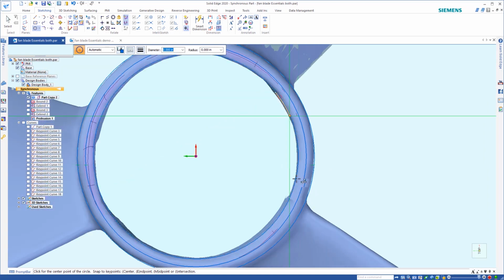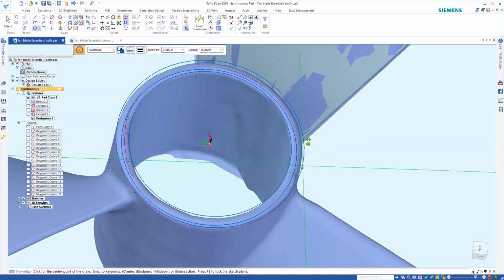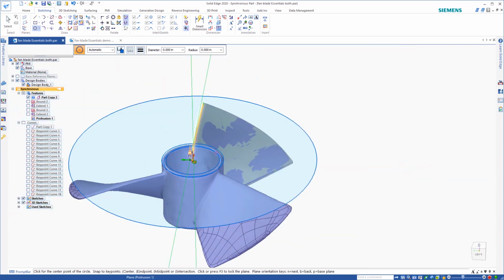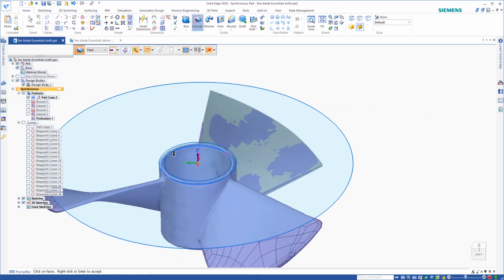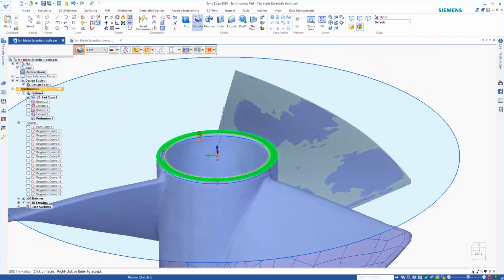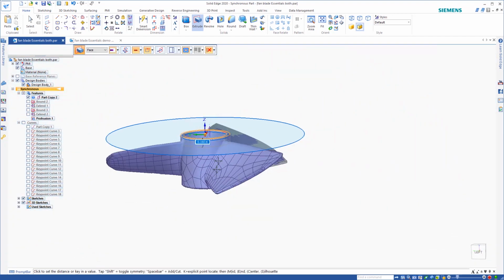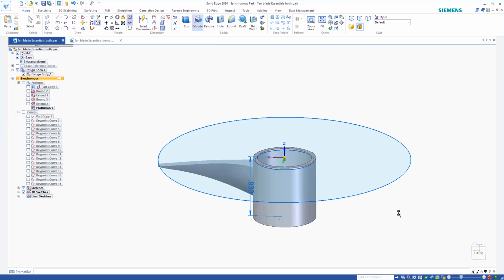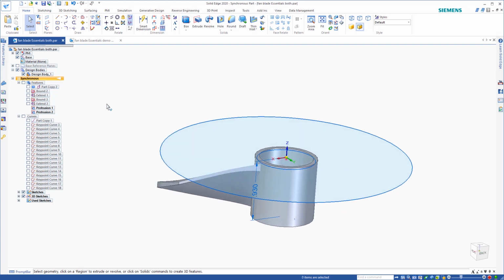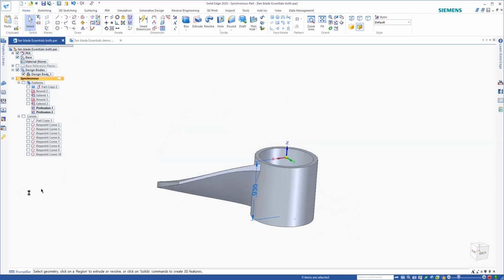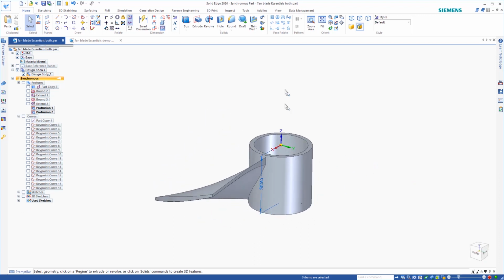And again, you can dimension it as you see fit. But you see that I just drew the two shapes. But you can redimension it like I just did earlier, and then come back over to extrude, grab this area here, and then extrude that. Let's do that 0.93. So there we have our shape. So now if I want to go ahead and turn off the curves, show the solid, now I can come over and just pattern the part to create a pattern of this blade around the middle.